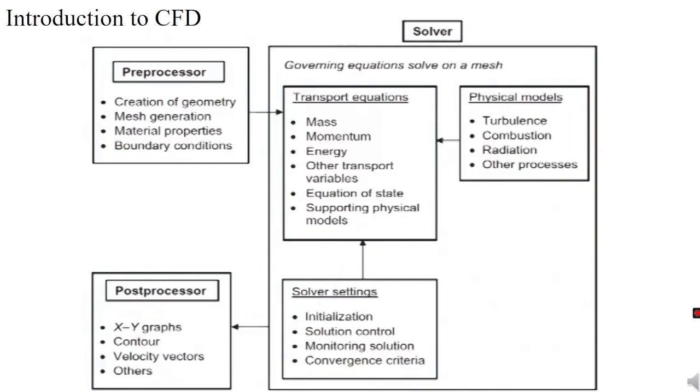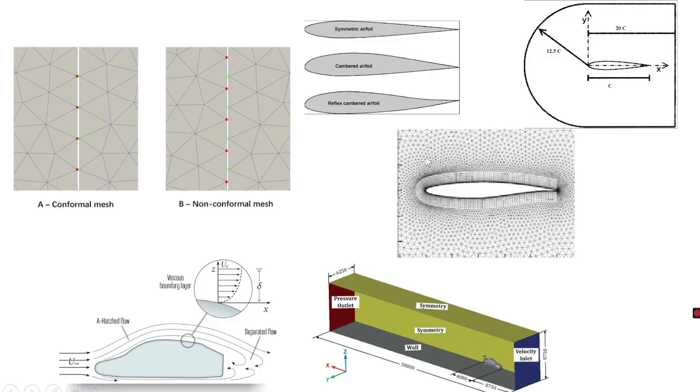To discretize the space, you can see it. This is the external flow we have. So we are not going for the discretization of the internal flow; we are not going for the discretization or meshing of the aerofoil. But whatever external domain we have, we are going for the discretization or meshing of the external flow, right? So mesh density should be aligned with the expected flow features, particularly in regions with high gradients, generally near the wall or boundary layers. Pay attention to the boundary conditions, whether they are periodic boundary conditions, ensuring a conformal mesh if possible.